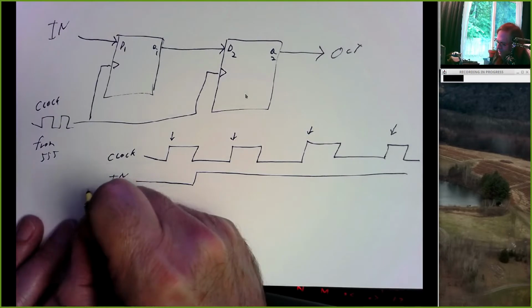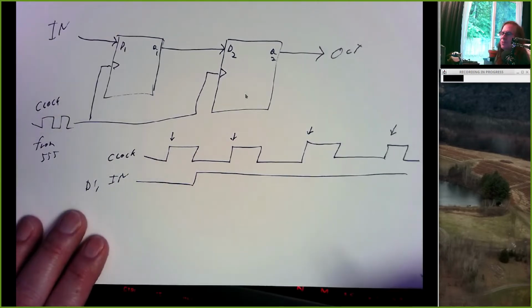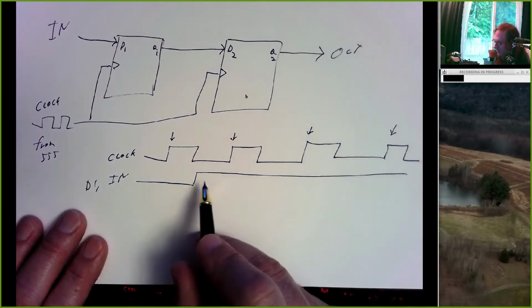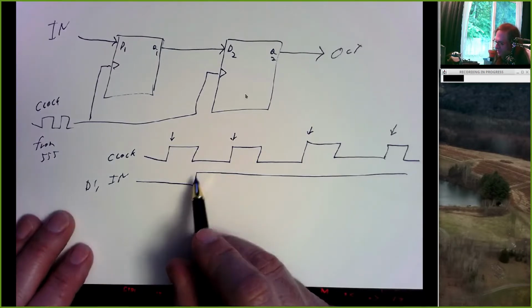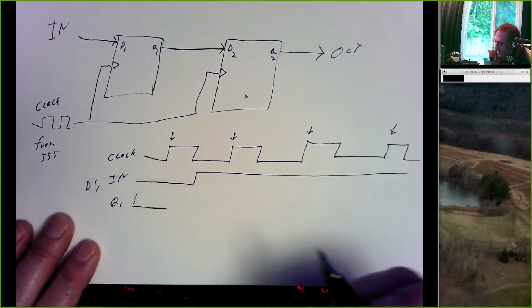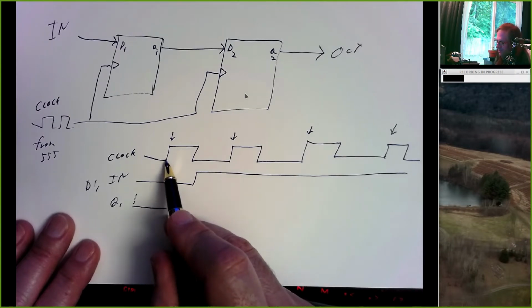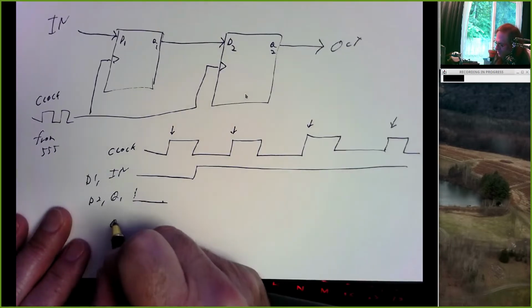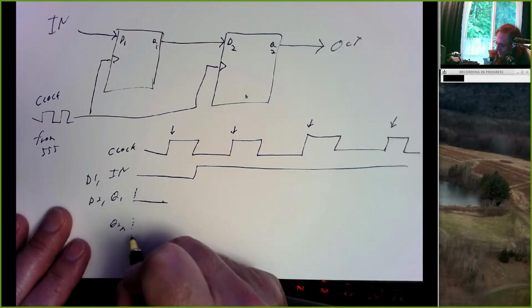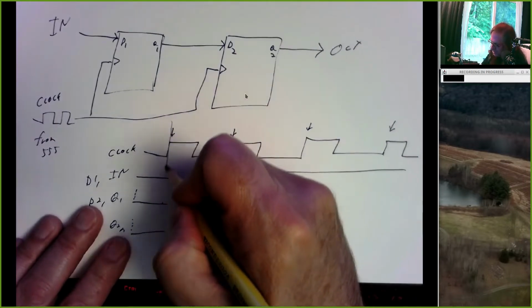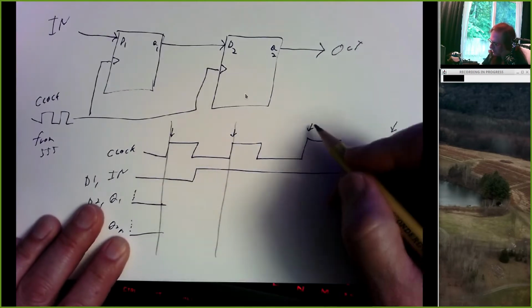Alright, well, that input is also D1, input of a D flip-flop. And we know a D flip-flop, nothing happens to the output until the clock ticks. So if I change the D input here, nothing's going to change. And so let's suppose that Q1 is initially low. And we know right here, the input's 0, so Q1 is going to be low. And Q1 is also D2, and if D2 is low, Q2 is going to be low. Alright, so let's look at these events.